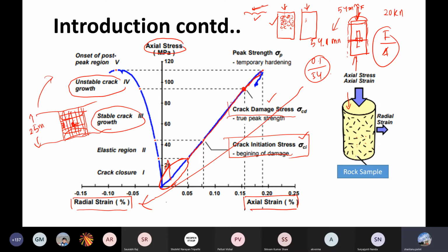I think we are going too much into it, but let me quickly explain. In each zone, the rock has a different boundary condition. Inside it is a triaxial boundary condition, and at the surface it is a UCS boundary condition. The UCS we are getting here is a property of the material, so when we are modeling, that is applied.